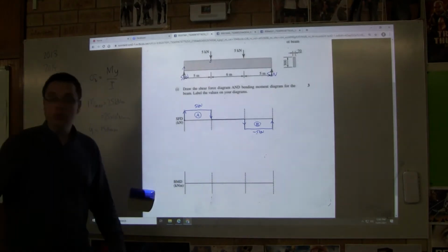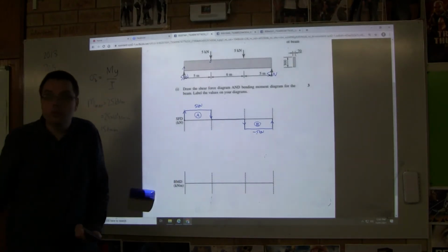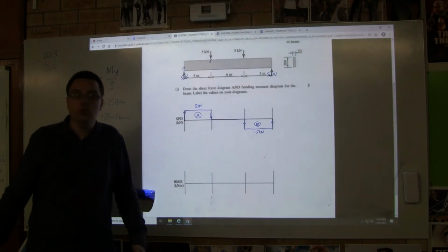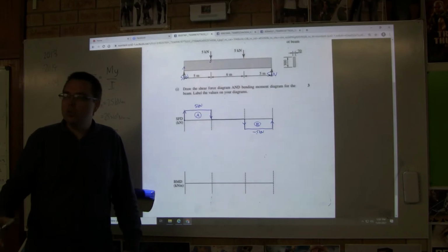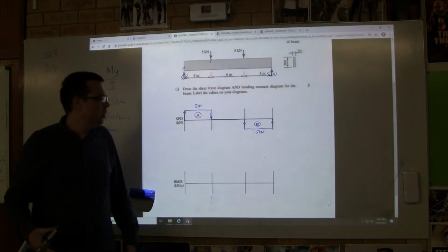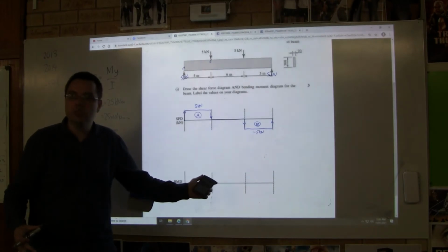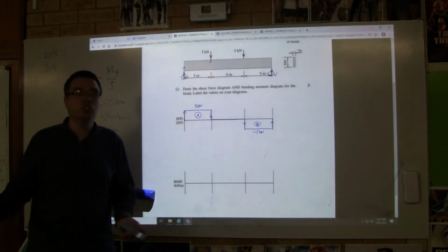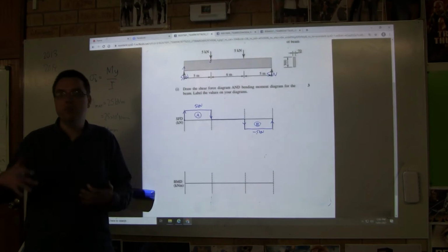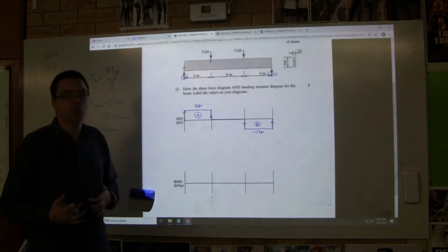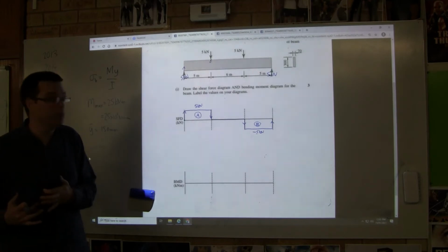The bending moment, you can calculate every single step along the way, and I remember doing that all the way through uni. And then, somewhere along the line, someone said to me, you know that you can just take the area under the curve, and it's going to be equal to it. And I'm like, that's genius. It just made my life so much easier. And then after that, in my professional life, that's all I did. And I've talked to multiple engineering studies teachers who did not know this little trick, right?